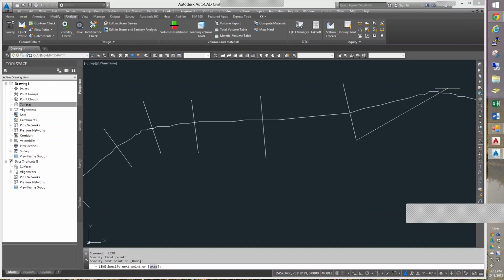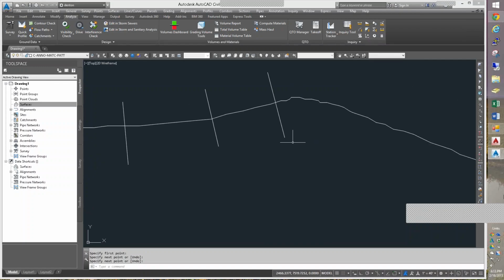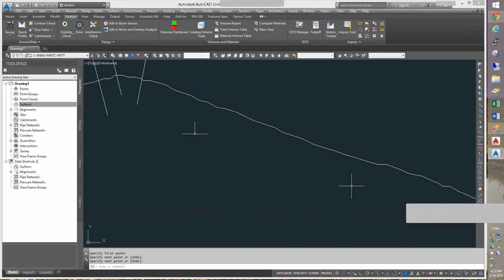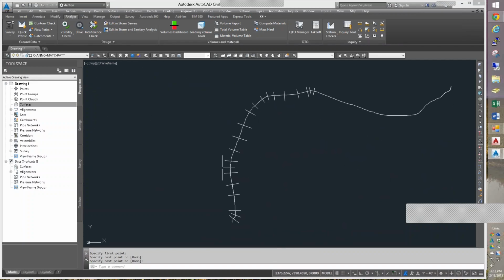If the channel shape is different from one cross-section to another, you may need an extra section. When there's a bridge, we typically would put a section 1 foot in front of the bridge, do both edges of the bridge, and then do a section 1 foot off the bridge again. That gave us a 1 foot horizontal distance to change what we do over the bridge. Well, hopefully you get the idea of what that survey is going to look like.